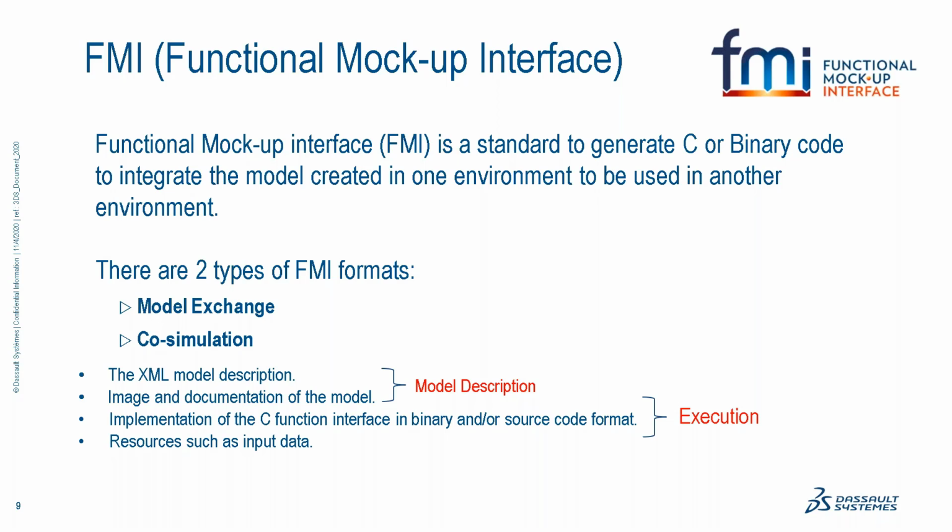In some cases, you may need to have the license or the tool that provided the FMU on the same computer, so it is using the license for running the simulation on the solver of that tool. In some cases, for example with Dymola or some tools, if it is a binary FMU or C code FMU, you don't need to have the tool on the machine where you are executing the FMU.